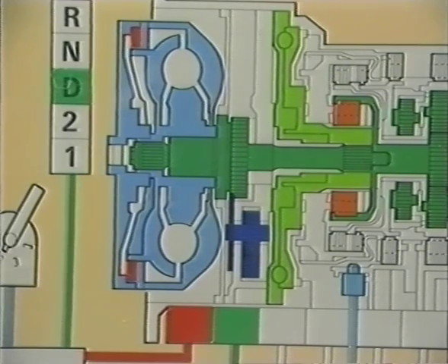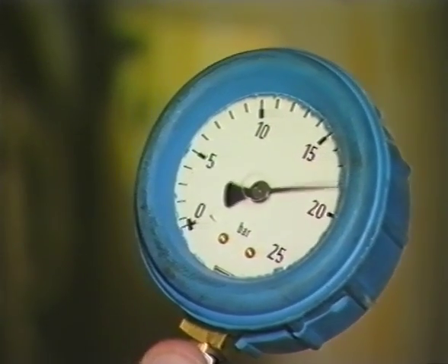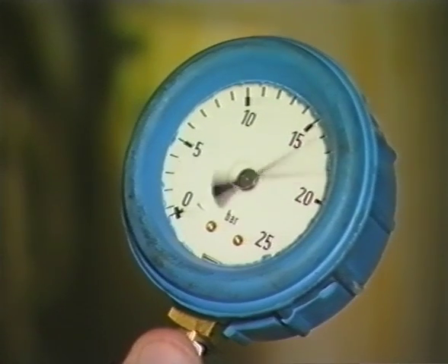If there is no pressure difference, and the gearbox is running at 18 bar continuously, this is an indication that there is a control fault in the lockup clutch.